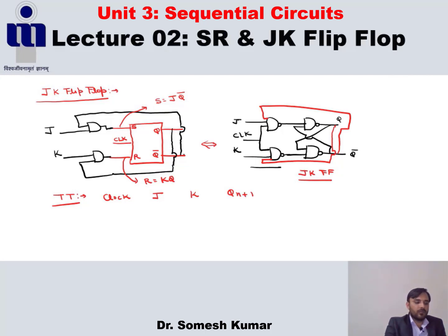Now what is the first case? If the clock input is 0, then this output becomes 1 and here it becomes 1. If both inputs of the NAND latch are 1 1, then our output remains as the previous state, that is our Qn, and this state is called the memory state, similar to the SR flip-flops.